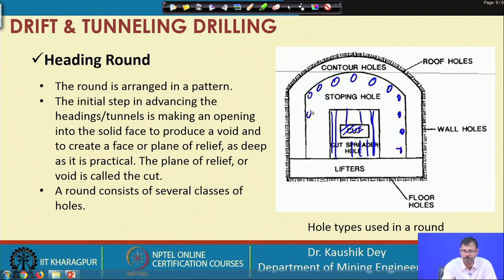So, that is the main production blasting carried out. So, the drilling must be carried out for the same, and finally, the drilling has to be carried out in the periphery area. Their objective is that there should not be any over excavation or over damage to the surrounding rock mass, so that the support cost should not be increased.